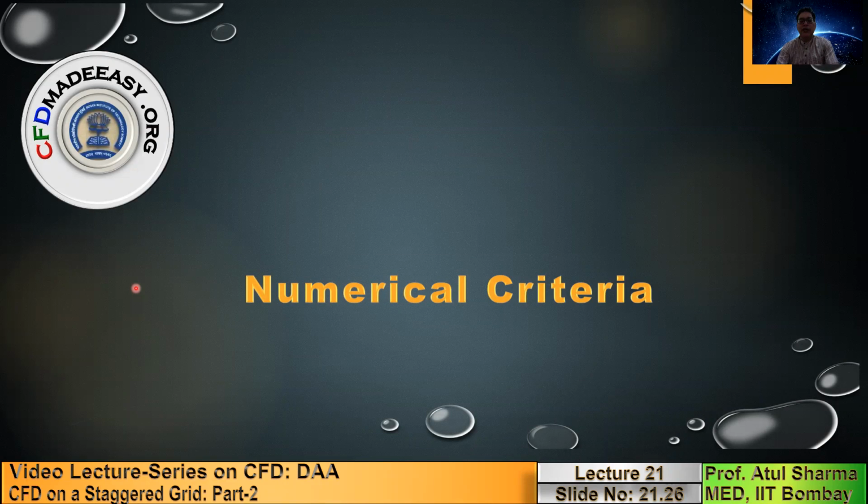So after presenting the semi-explicit method, where I presented the predictor step and the corrector step, in the predictor step, we had predicted velocities and then multiplied by density to obtain the mass flux predictions. So we obtained U star, V star, MX star, MY star.